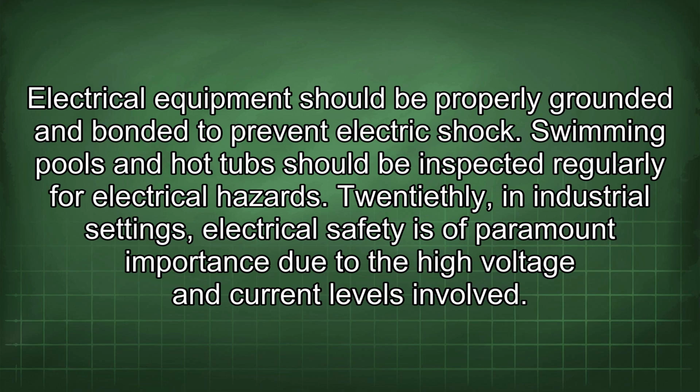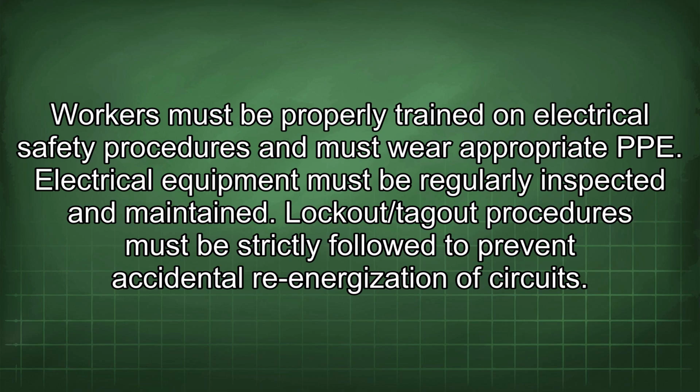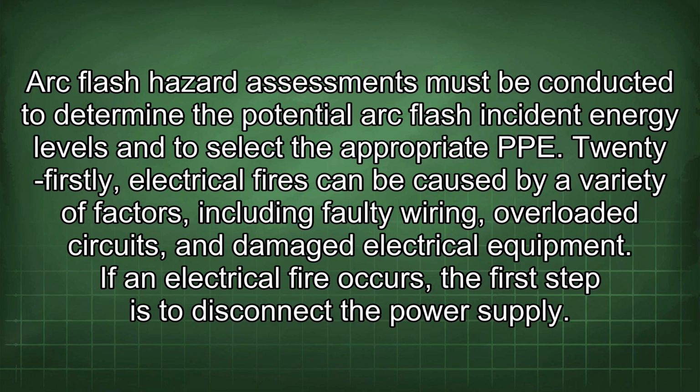Twentieth, in industrial settings, electrical safety is of paramount importance due to the high voltage and current levels involved. Workers must be properly trained on electrical safety procedures and must wear appropriate PPE. Electrical equipment must be regularly inspected and maintained. Lockout/tagout procedures must be strictly followed to prevent accidental re-energization of circuits. Arc flash hazard assessments must be conducted to determine the potential arc flash incident energy levels and to select the appropriate PPE.